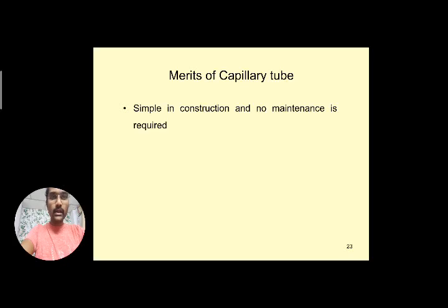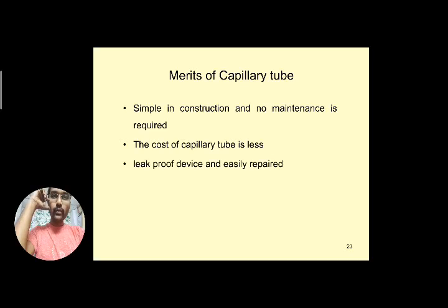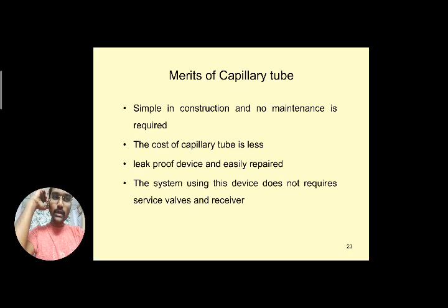Okay, and if you see some merits of the capillary tube, it is simple in construction, and no maintenance is required. The cost of the capillary tube is less, it is a leak proof device and easily repaired, so very easy to repair. And the system using this device does not require service valves and a receiver. Okay, no need of any receiver here in the system. So this capillary tube is very effective, and it doesn't require any service valves and receiver.